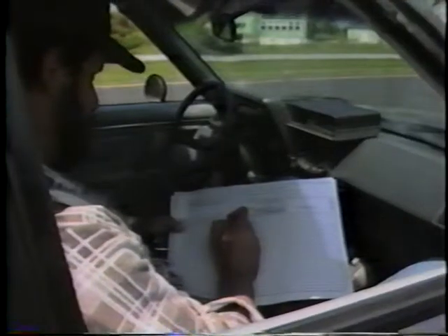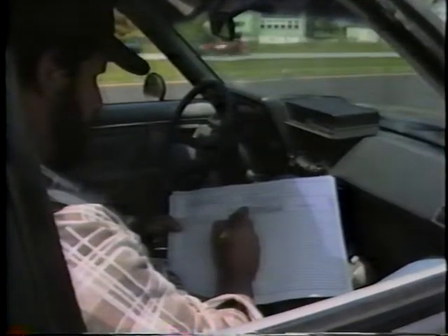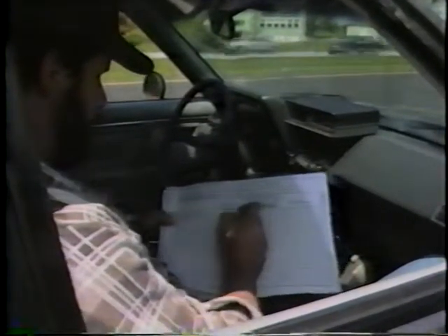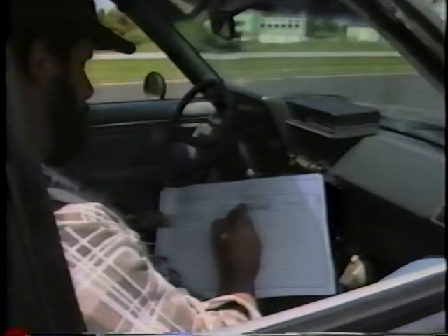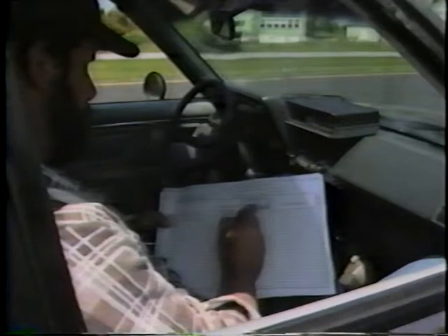As part of the inventory, each sign should be evaluated, judged for conformance to the standards of the state's traffic control manual, or the MUTCD. In addition, transportation officials should conduct nighttime reviews of all traffic control devices on a regular basis. We emphasize the need for nighttime reviews and looking at these devices at night. Once again, Phil Russell.